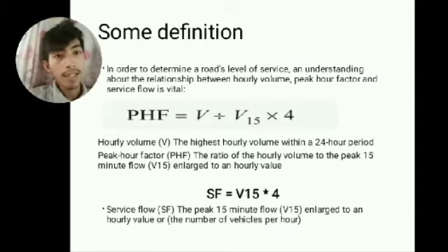We have another formula, SF equals V15 times 4. The SF is what we call service flow, the peak 15-minute flow V15 enlarged to an hourly volume, or the number of vehicles per hour.